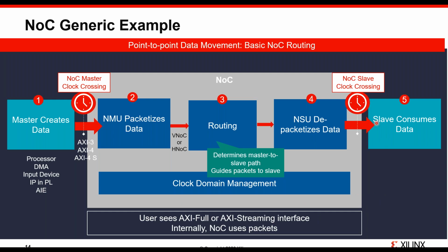So that is a fairly simplistic view of it as we work our way through, but one of the things you might glean out of this is that the NoC master and the slaves are actually fully responsible for the clock crossing domain between those two points. And it is handled seamlessly for you. You don't need to worry about it. So no matter what the rate is on this side, it will translate it into that gigahertz or faster for the majority of them as the flits work their way through the device.